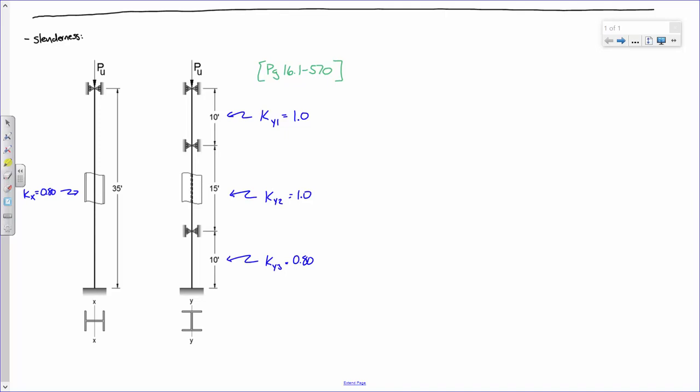And so when you do this, you're going to repeat this calculation for as many different bracing lengths as you have. The x-axis, what you're after is this. You're trying to determine not the longest length, not the biggest K value, or not the biggest radius of gyration. What you're trying to figure out is the biggest KL over R. Okay? So we're going to compute 1 KL over R over here and 3 KL over R's over here.